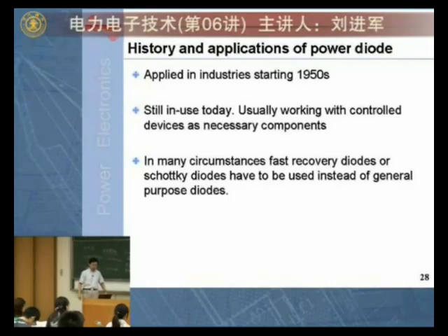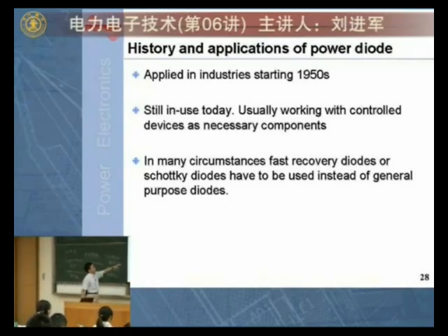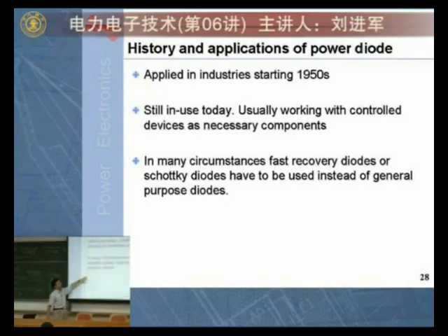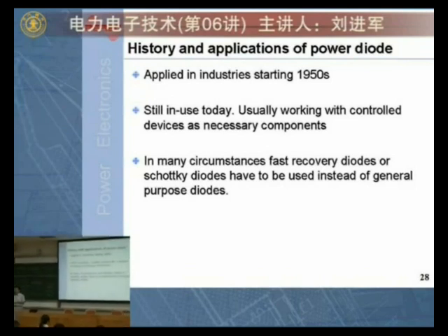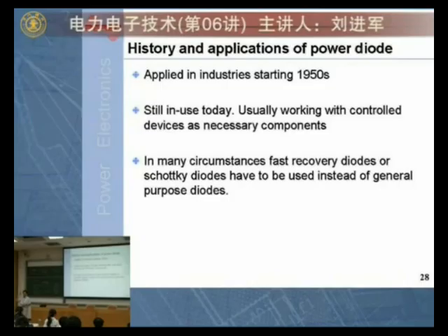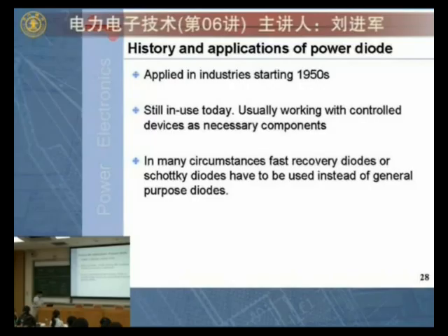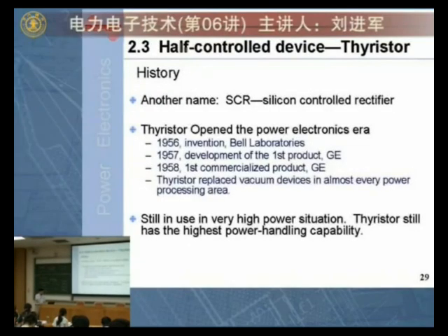Okay? And in many cases, fast recovery diodes or Schottky diodes have to be used instead of general purpose diodes, because in many cases we need this diode to be turned on and turned off much faster. And therefore, you need fast recovery diodes or even Schottky diodes. Okay, that's all about the power diode.